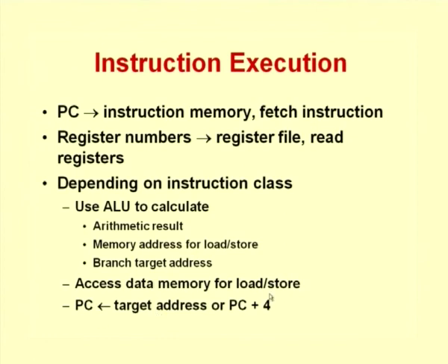Note that we are trying to do a little bit more work with the ALU, not just the arithmetic and logic functions required for an arithmetic logic instruction, but also using the same ALU for calculating addresses wherever we need them. When we look at load store kind of instructions, remember that we need to access data memory. So, we need a mechanism by which we are able to access the data memory when a load or store instruction is encountered. And when it comes to the jump instructions, which are conditional, either we will have to jump to the target address, or if we are not jumping, we need to go to the next sequential address. So, the program counter will have to be either updated with the target address.